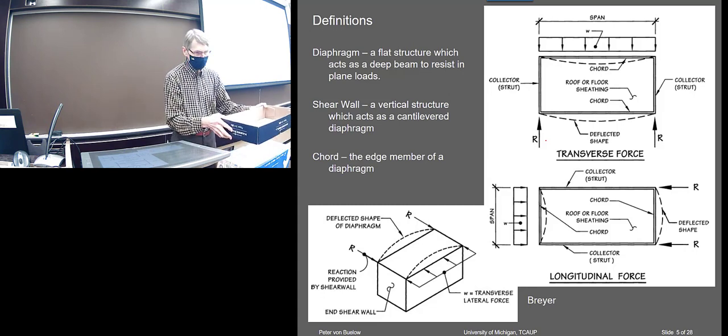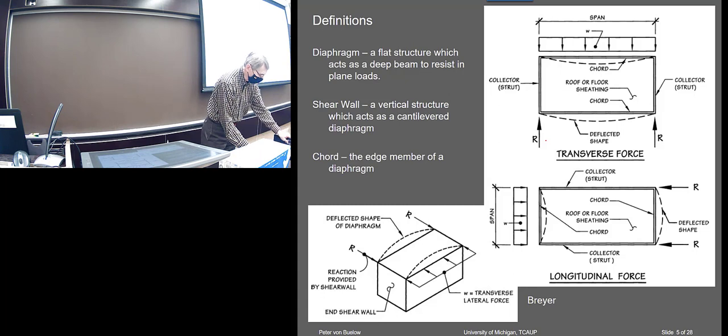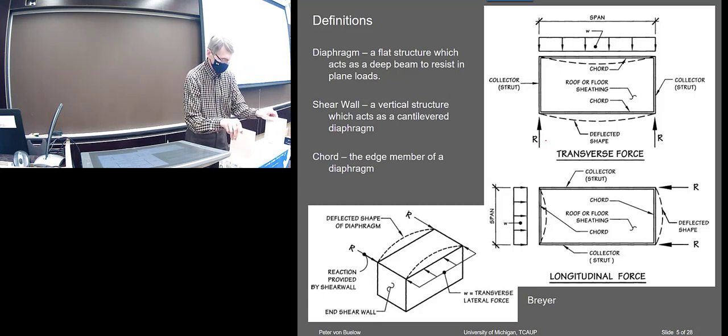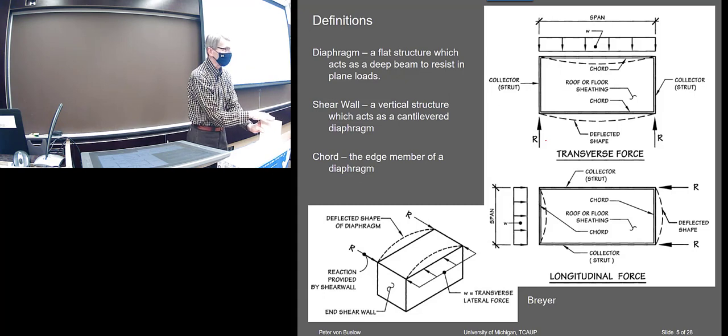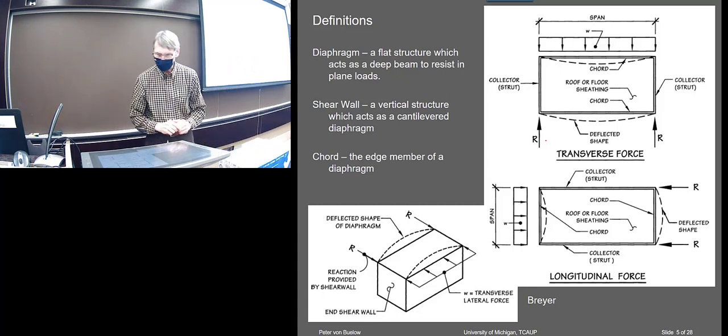Right, so that's the diaphragm. The shear walls are what's attached to it, right? They're over here. Oops, I guess we need a couple more, and this is then the collector strut. This would be at the top of the shear wall, the collector strut. The shear walls in shear, you can see one side's going to be in tension. It's got to be held down, and the other side, as it gets that shear applied, there's a moment, right, that's twisting it, that would push it up.